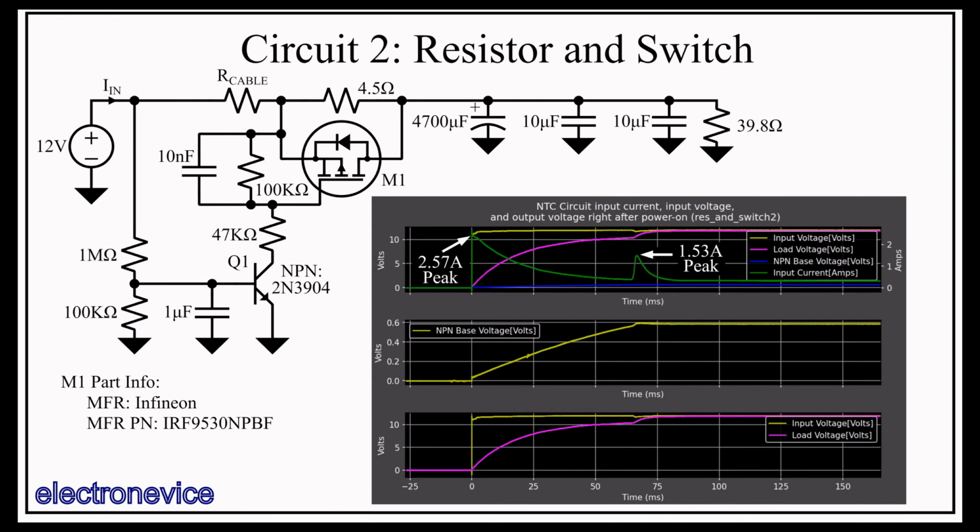So it can be difficult to determine analytically how high that spike will be, and if it remains within the requirements of your circuit. And it's best to try to minimize the voltage drop across that resistor, as that helps to minimize the spike height overall, and thus our tolerance to its uncertainty increases as well. So this circuit really only works well if that series resistance is not dropping the voltage much after the input capacitance is charged, when the only current is steady-state non-capacitive current.